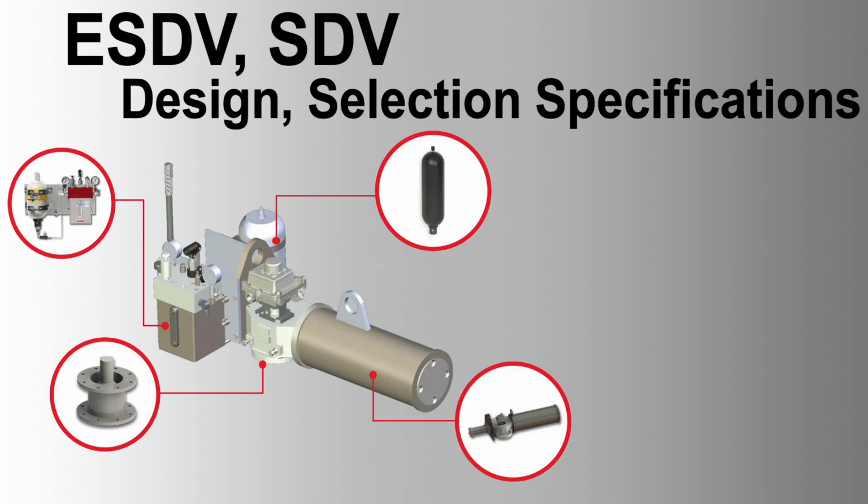4. Positioners. Function: ensure accurate valve positioning for control applications. Selection: digital or analog, compatible with the control system, and capable of handling the operational environment. Considerations for medium and high-pressure scenarios. Valve sizing: ensure the valve size matches the pipeline and process requirements to minimize pressure drops and ensure proper isolation.